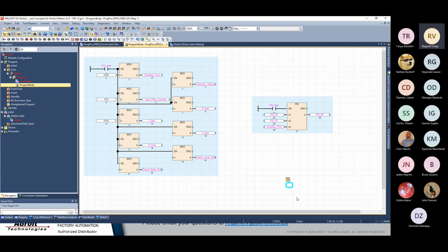So why am I using K's here? K means integer in this case. In bit manipulation, the K means nibble. Each K is a nibble, which is 4 bits, but we don't have to worry about that here. Here we're only looking at integer values. Yes, you can use real values as well. There'll be some conversions to be done, but for simplicity's sake, we don't want to sit here next week. We're just going to use integer values.